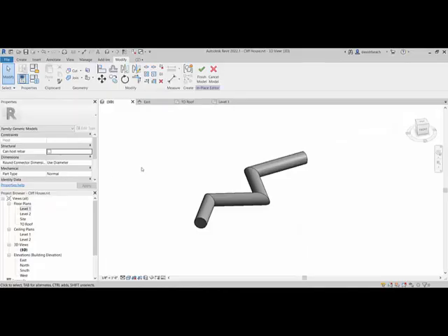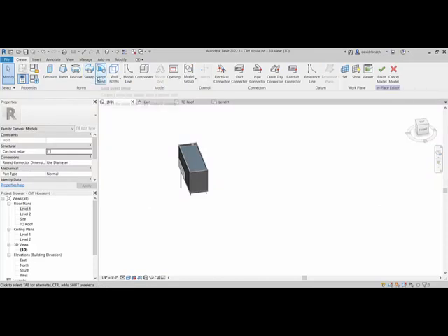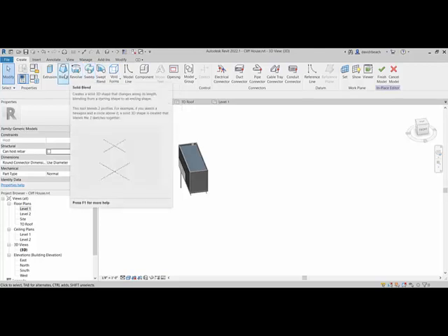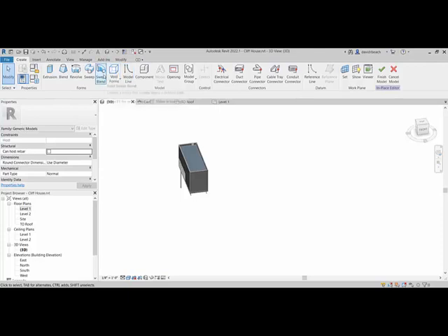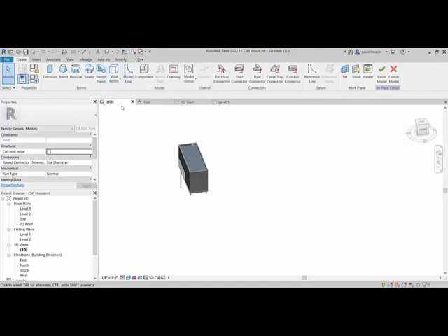Okay. So let's go ahead and apply that technique. Oh, last Revit tool, but I'm not going to cover that right now, is swept blend. So that's the same thing as this sweep, except I have two reference planes, just like blend does. I can put one shape at the beginning, one shape at the end, and that will put those two things together for me. Okay, I have only found a handful of uses ever for it in terms of doing models, but when you do them and you need them, it's really nice to have them, right? So it's not one of those things I use very often, but it's pretty cool that it's there.